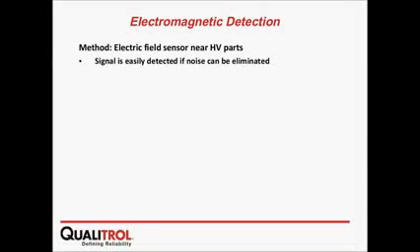If you don't eliminate that, and you have PD at a lower frequency than that, it will cover that PD, and you don't want that. You want to have a clean picture of your PD, eliminating all that background noise. So your partial discharge measurement must have the ability to eliminate all the noise.